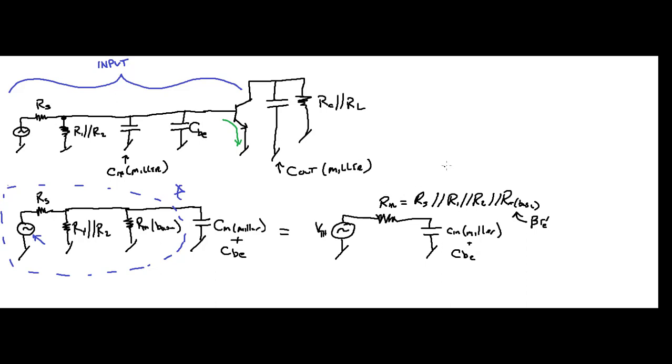So think about it. If you want to know the critical frequency, you know what R is. FC upper, right? And that's at your input. This is your input. That's going to equal 1 divided by 2 pi RC.